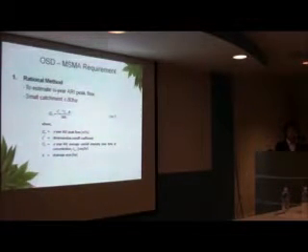This formula is used to calculate the Q of pre-development and post-development. This formula is very simple to use. So MSMA recommends, the first method is the rational method. The rational method is being used to calculate Q.